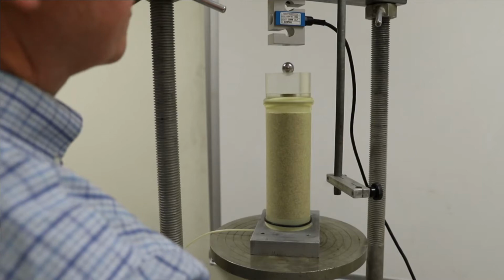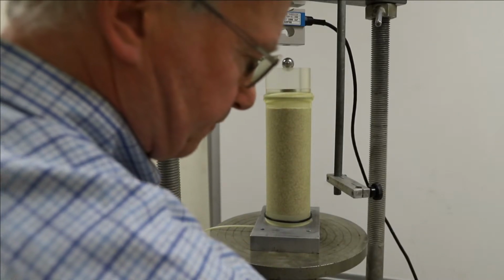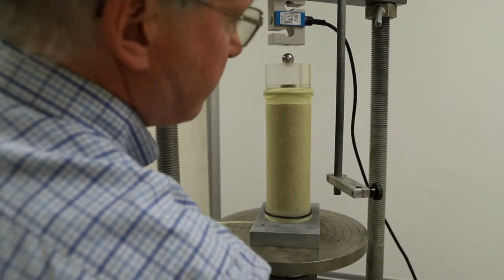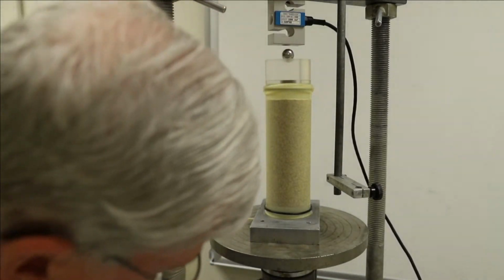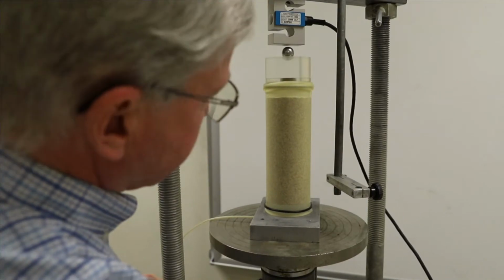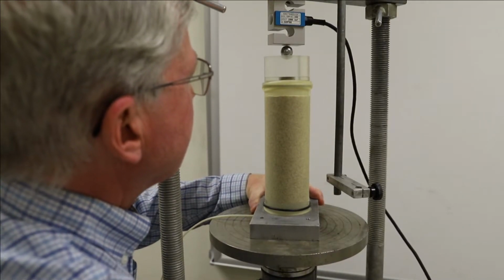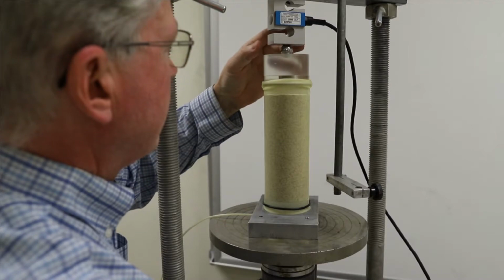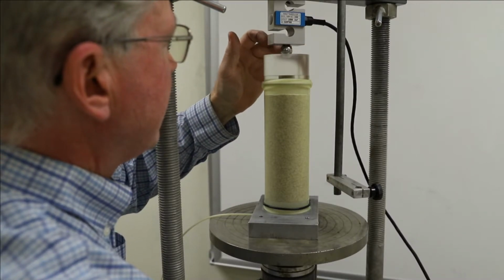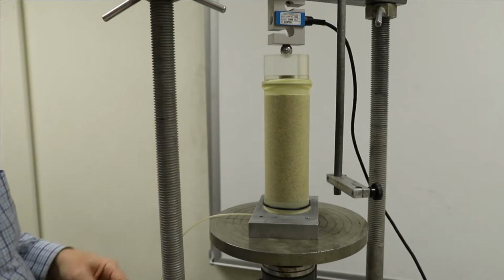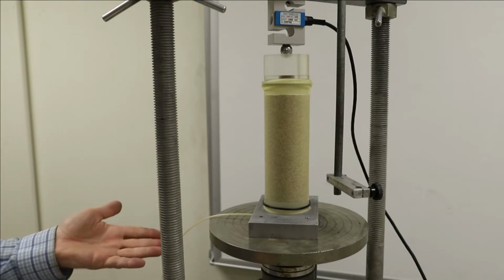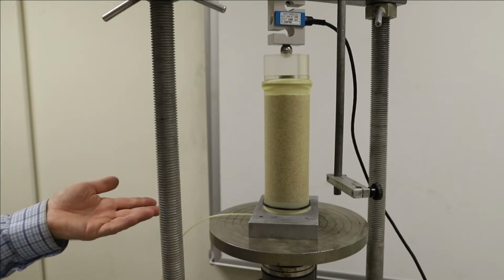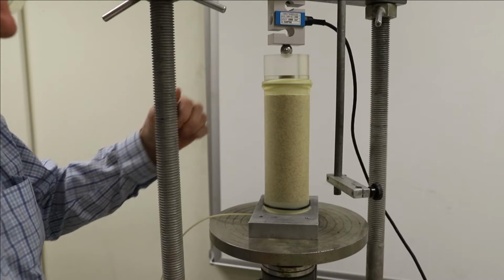And I can do that with this wheel. Bring it up close. Make sure this is in the right place. I'm going to leave a small space so there's no contact between the system and the sample. So when we start the machine, we'll have a little bit of data in the data file that we acquire with the computer where the table will be moving, but we won't be measuring any new load because there's still a gap in there.